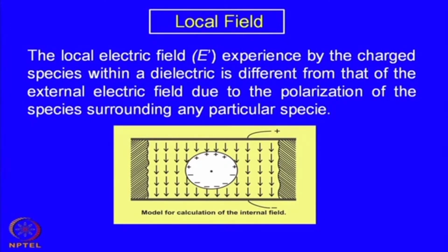Now, there is also a concept of local field. The local electric field experienced by the charged species within a dielectric is different from that of the external electric field applied from the outside, due to the polarization of the species surrounding any particular species. Okay. What if we want to find out the electric field experienced by this particular charge species when electric field E is applied from outside?